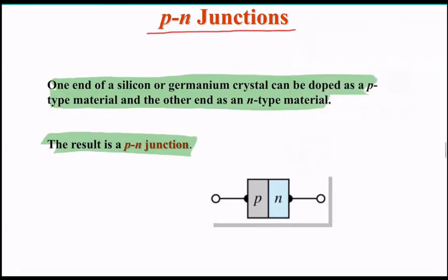Say you can have both materials, P and N, here. These both can be silicon. I can just write Si here, and these both could be silicon. If I dope this silicon with an element that has more holes, more positive charge, then this would make a p-type material. If I take silicon and dope it, basically mix it with a material which has extra electrons, then I would have extra electrons in this region, like this, and it would make an n-type material.